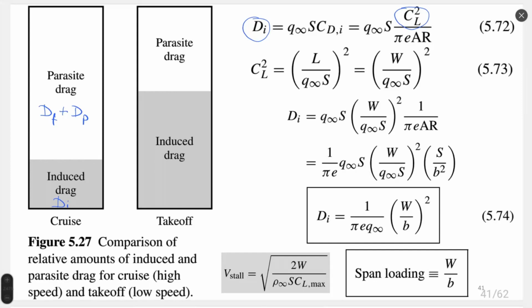And then recalculating lift coefficient from point of view of weight of airplane, we see that induced drag, according to equation 74, would be proportional to weight of airplane. Since it's proportional to lift coefficient, of course, lift and weight should be compensated on takeoff, and drag force would be proportional to weight force of the airplane. Equation 74. Higher weight, higher drag.